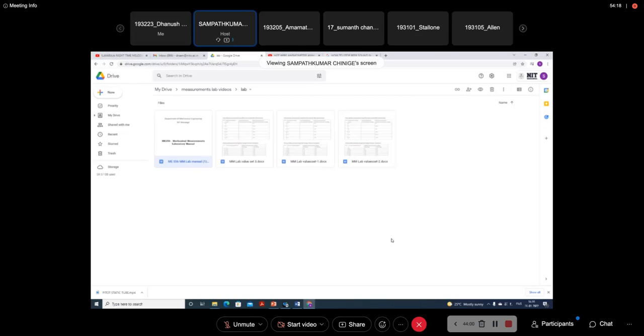There's absolutely nothing preventing it. But if you use it for some oil flow, for example, what happens is that this is basically for gas flow. We will generally use this vane type for gases. If you want to use it for liquid, what is the problem? You tell me. Liquid will have more density, and for a more dense fluid, if it hits, it gives an impact.